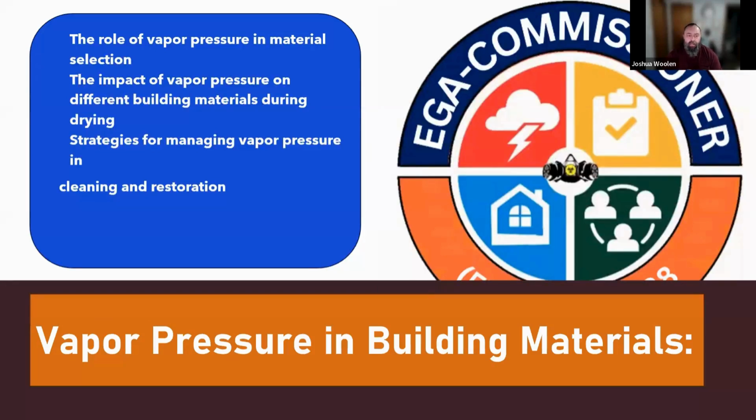Now, the role of vapor pressure in a building material is crucial for managing the moisture. And a lot of that, again, is to prevent wood from shrinking, twisting, buckling, and all the other things that go on with wood materials. And it doesn't matter. It could be a seal plate, a stud, a support beam across the top, as well as mold and bacteria in this environment that gives rise to malodors, right? Like basements and stuff, or crawl spaces, and many other spaces.